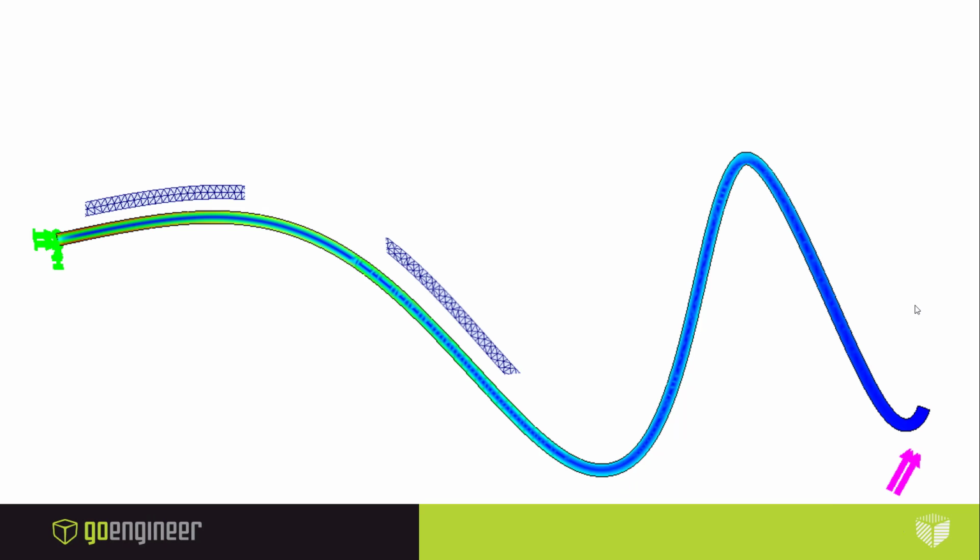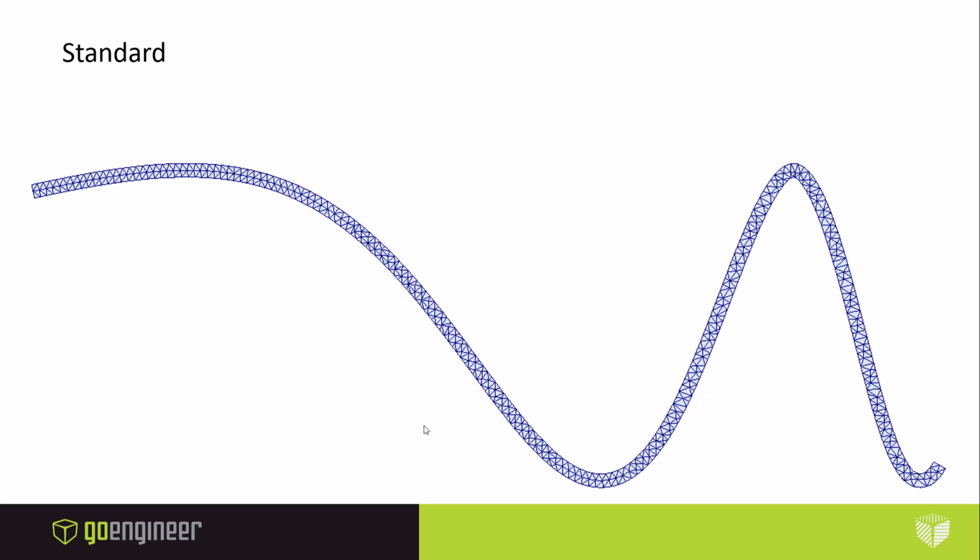Why it's advantageous for a mesher to focus on good aspect ratios is to give us more consistent mesh flow. You can see what mesh flow can do to your results. In this region, we have nice, even 2 elements through the thickness, and you can see the results are nice and smooth. However, in this region, you can see the elements get misaligned, and so the results end up getting a little fuzzy here.